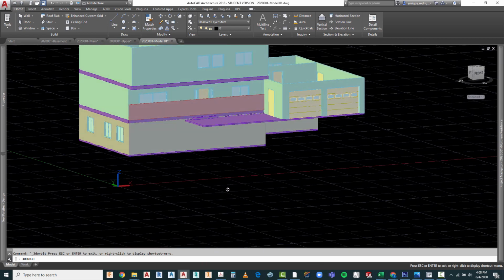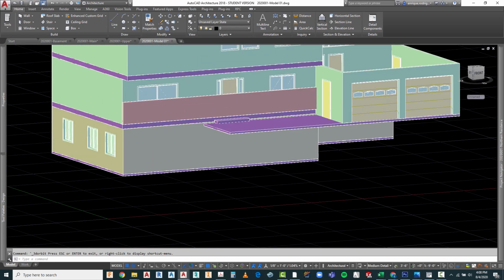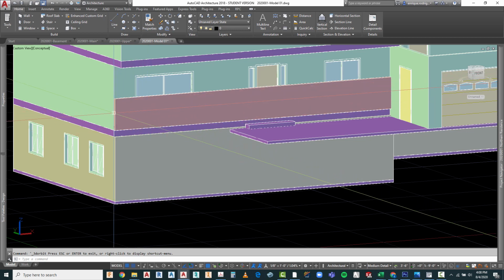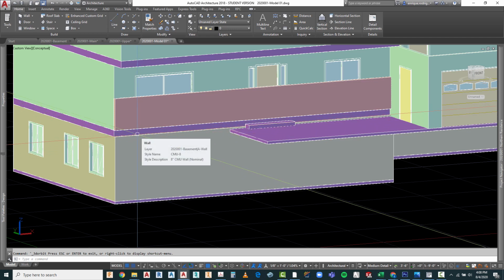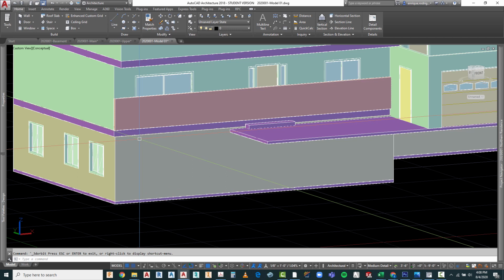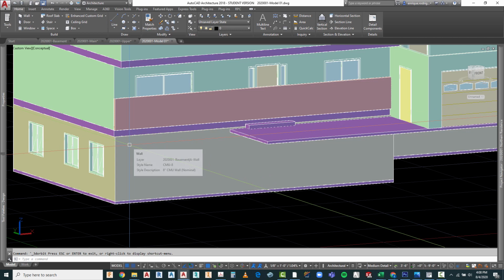So what we want to do is make sure that this wall is going to disappear into the ground. When we draw our wall section, you'll see that even though this front wall is a 12-inch CMU block, the last block is an 8-inch. So it creates a 4-inch ledge for this to rest on. So this actually needs to go about 18 inches down into the top of this wall.